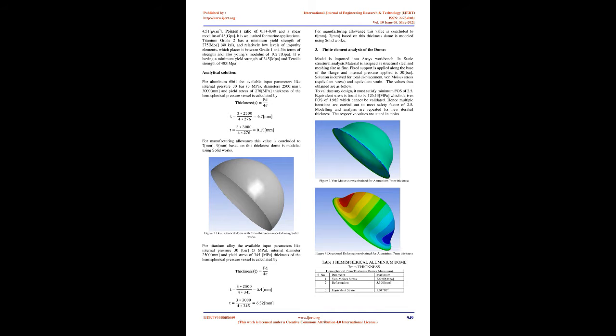Hemispherical dome, or heads. The head depth is half the diameter of these heads, which have a radial geometry. Two pressure heads are arranged back to back in these storage heads, forming a storage sphere that efficiently stores materials under high pressure. Hemispherical heads are thinner than shell heads and have a standard code 3:1 taper during the transition. Hemispherical heads are usually made from welded sheets rather than the flat sheets used in the other head varieties. This makes it the thinnest head on the market, as well as one of the most expensive. These heads are ideal for applications that need high-pressure storage or vessels with enormous diameters.